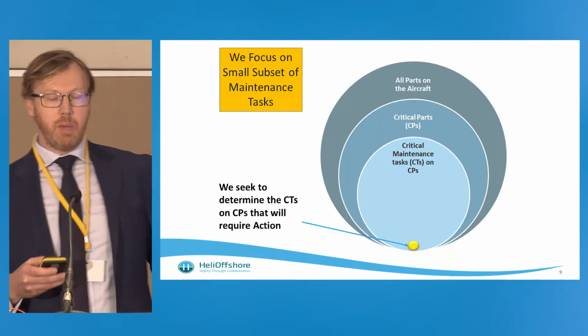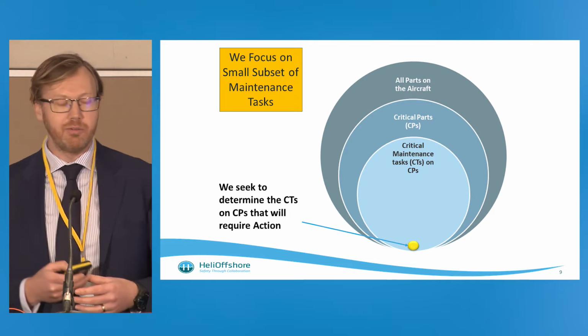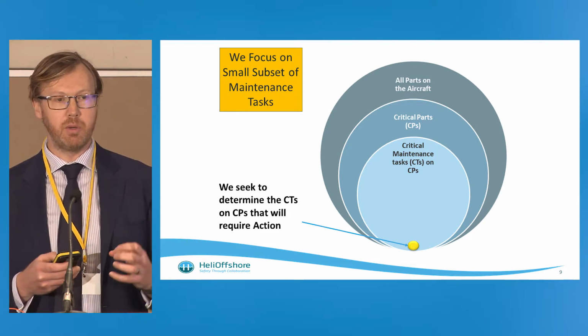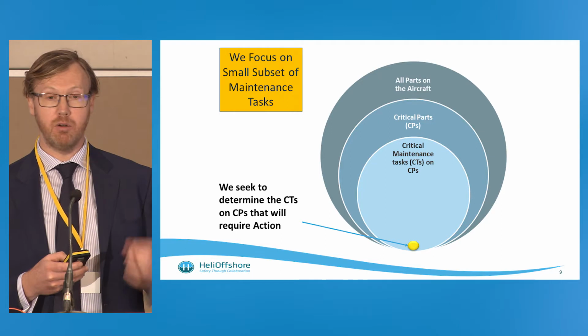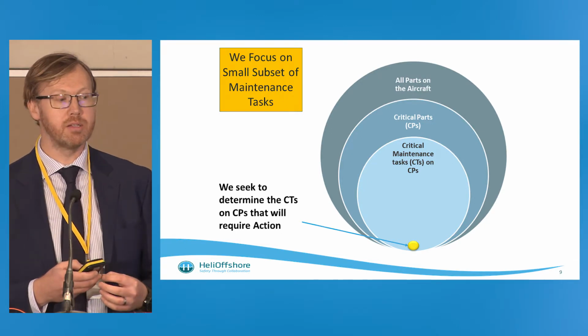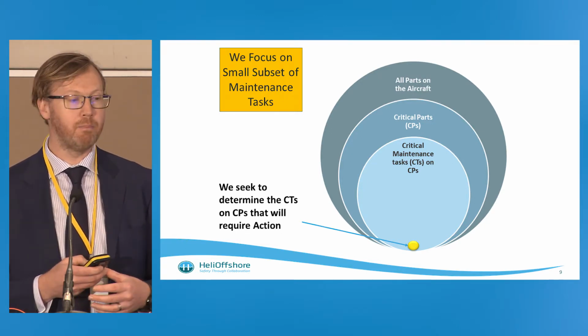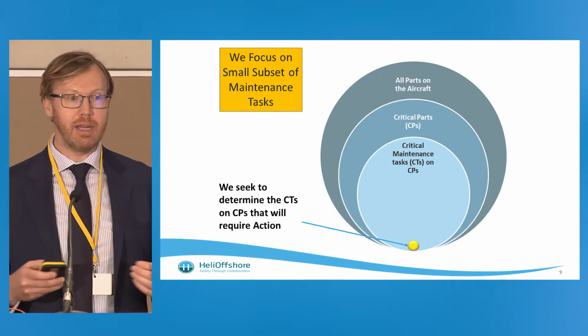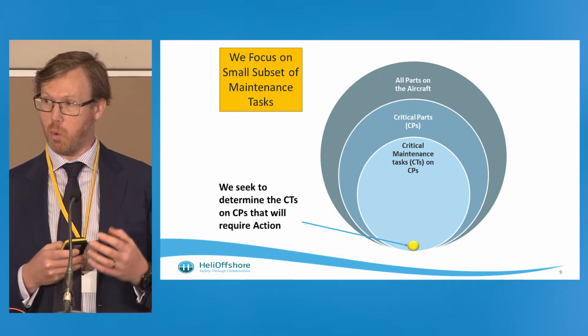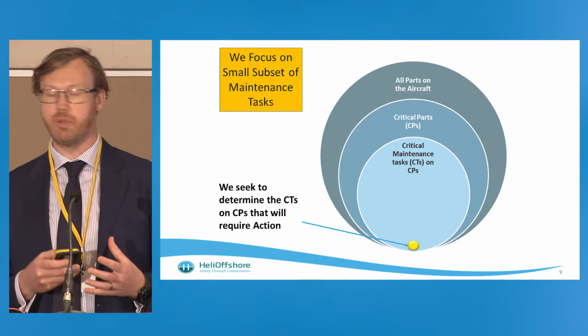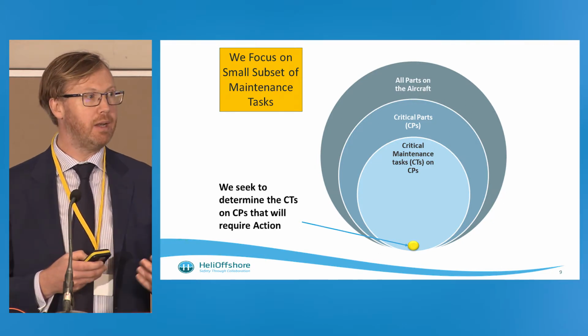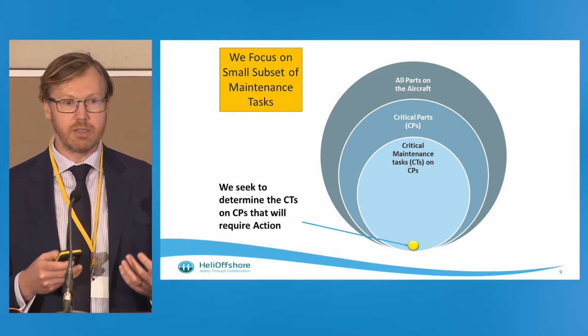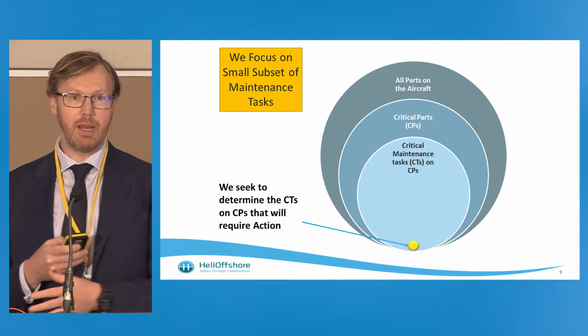So clearly, we're not going to be able to look at a whole aircraft. So what we do is we focus down on critical maintenance tasks on critical parts. So we spend time with the OEM to actually break it down and actually focus on what is critical, what do we want to be spending our time on. Now, clearly, the removal task isn't critical, so we eliminate removal tasks.